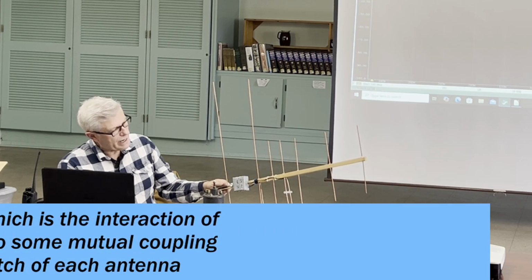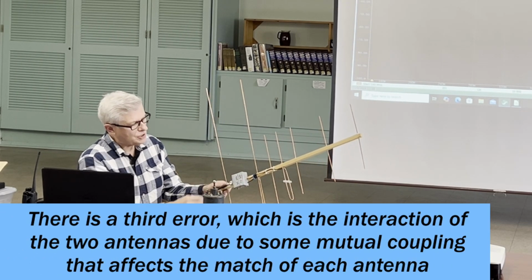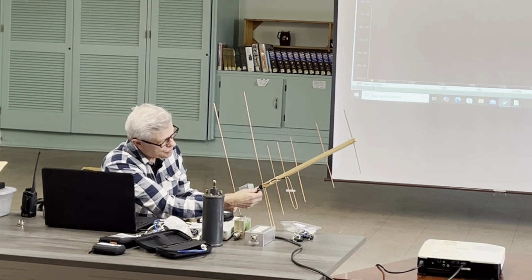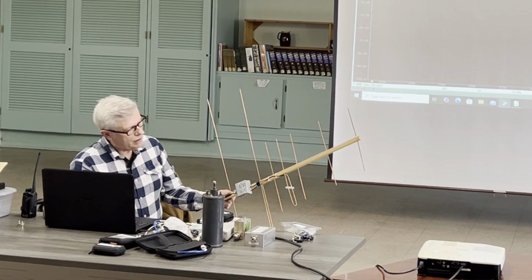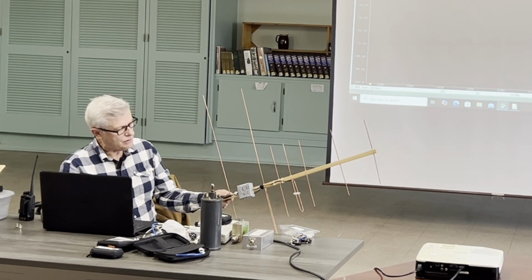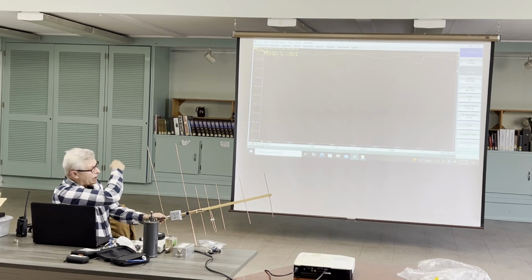The way you figure that out is, again, this is a device under test, this box. So what you could do is connectorize these 2 cables, and measure the box to see where the band passes. Now remember, we're looking at return loss. That's why it's dipping down.